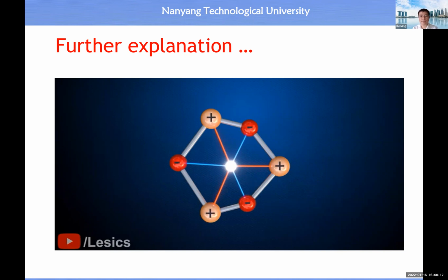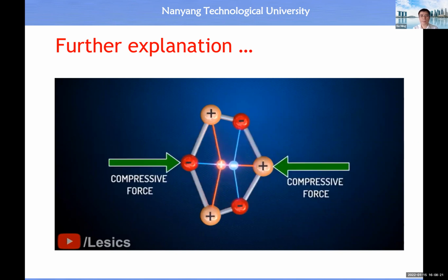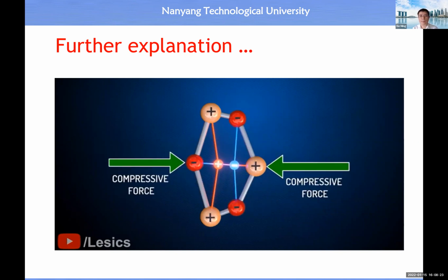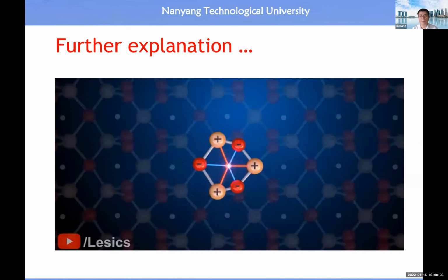The center of charges do not coincide anymore, and there will be a charge separation. This is called polarization. This also means an electric field will be created between the net positive and negative charges. This leads to generation of a small voltage across it. The quartz structure consists of multiple similar hexagons connected in series, which lack a center of symmetry.